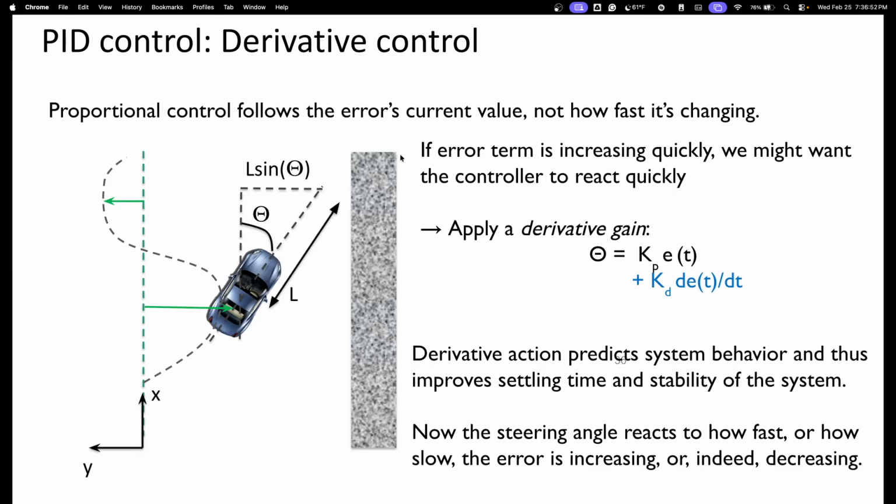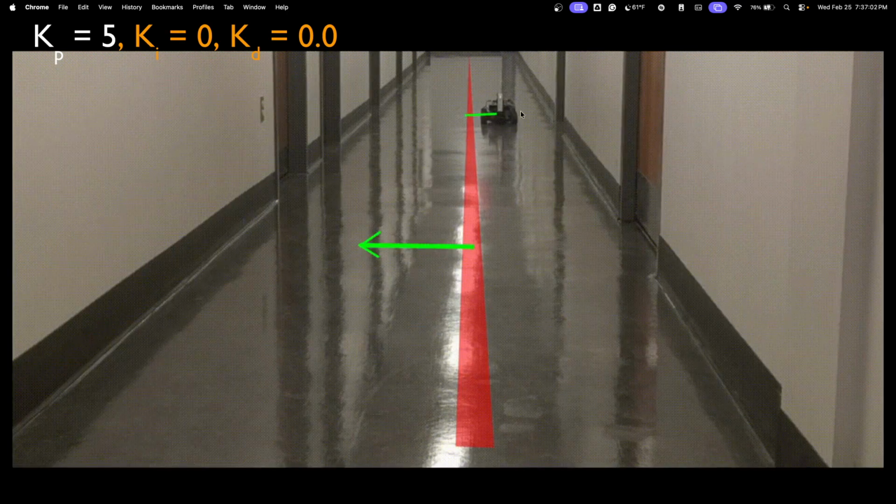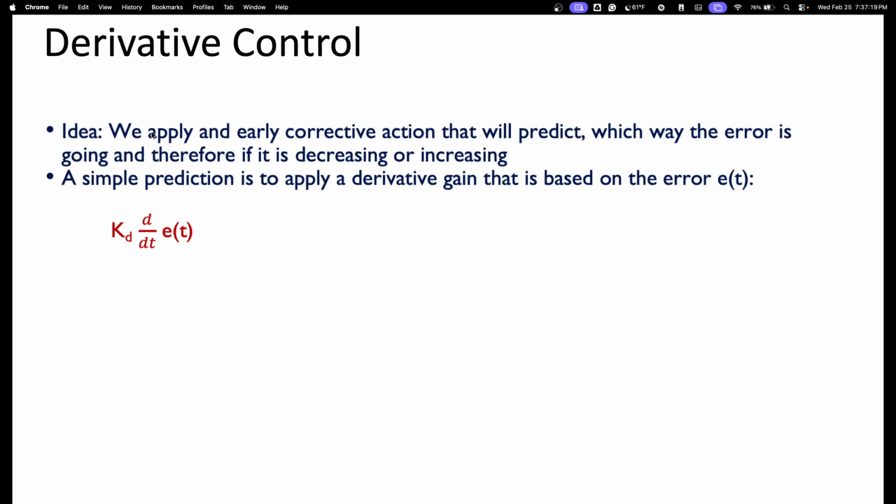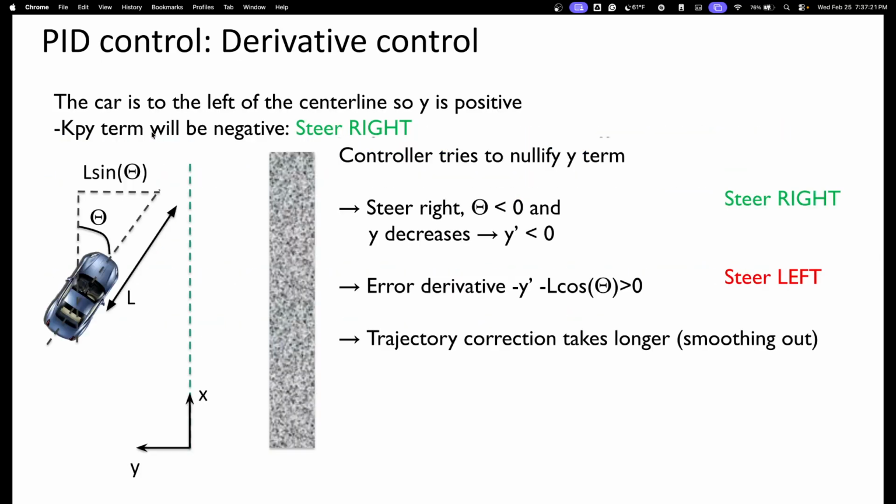And this is explaining how you would need to adjust the derivative controller and what it does. The derivative controller is just kind of like a damping, to avoid it from oscillating like it's doing right now. The goal for the derivative controller is, we are approaching the set point, so let's reduce the input so that we don't overshoot. Overshoot is like you get there and then you still continue to go. So that's what the derivative controller is doing.